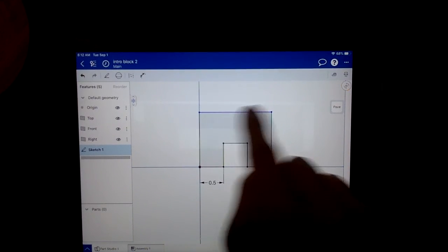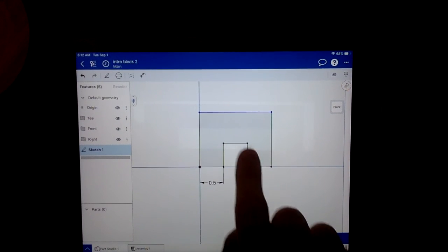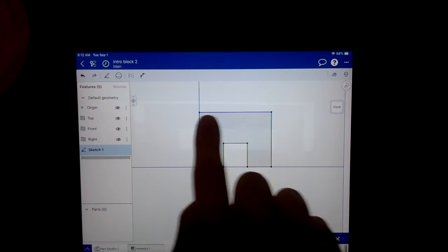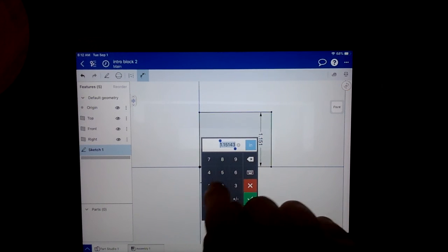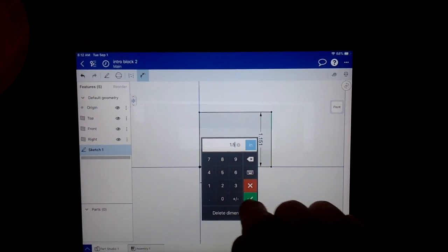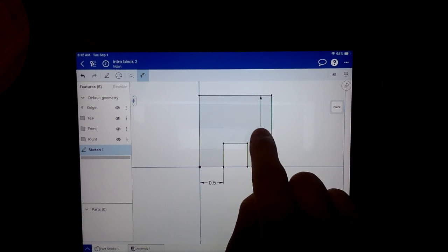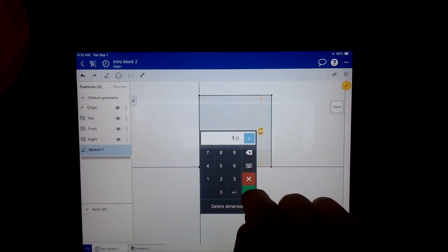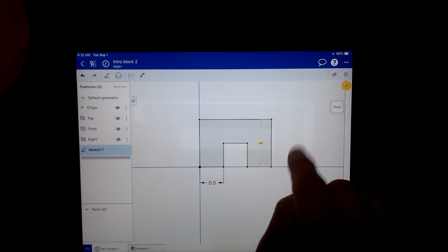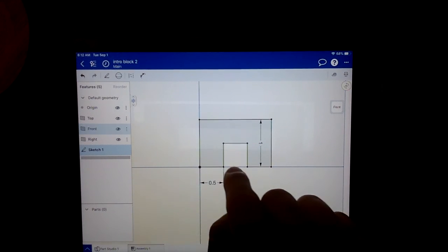So because it already knows the width of that line, right? If that's 1/2 inch, that's 1/2 inch, that's 1/2 inch, that blue line has to be 1.5 inches. It's just the location is what's off. So I'm going to give that a 1.5 inch height. Oh, sorry, not 1.5, 1 inch, because it's 2 blocks tall. There we go. So there's my first sketch using the geometric constraints.